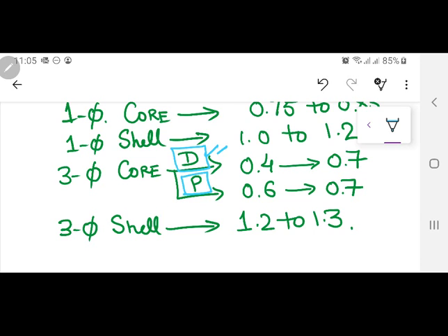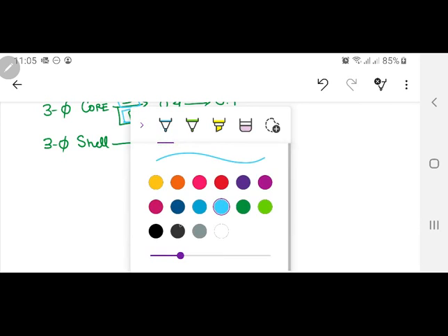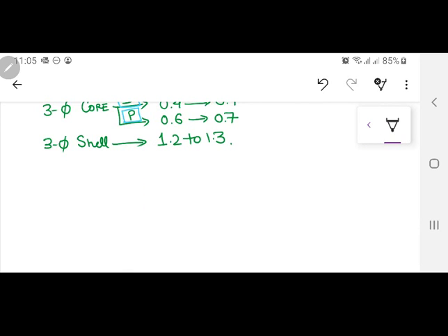Now, one thing very important which must have been told to you in your machines course also: whenever a transformer is written on the nameplate rating, they will write it as 11 kV/400 volts. Now, these are line to line voltages. If you make the mistake of taking them as phase voltages, you have destroyed your design from the very first phase, because all the windings are designed phase-wise.